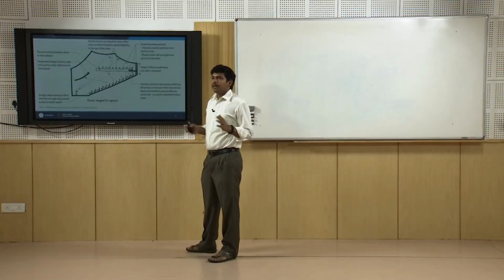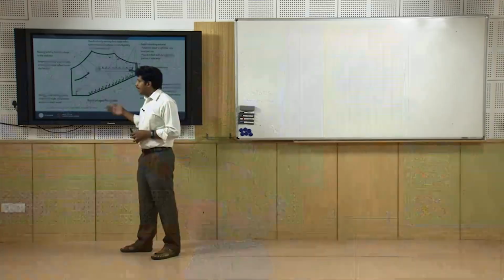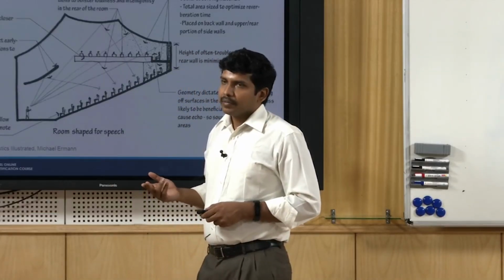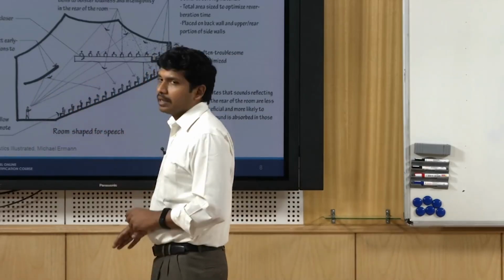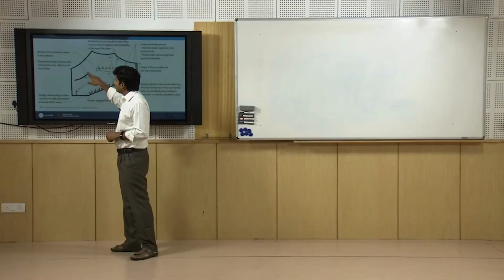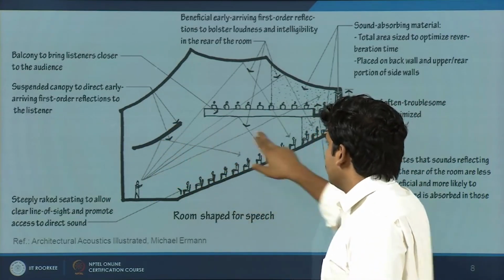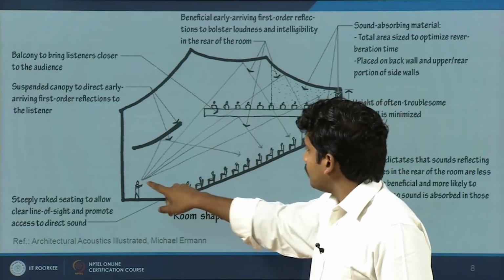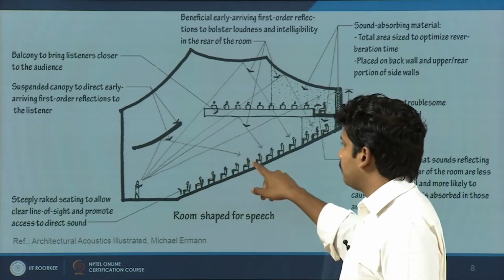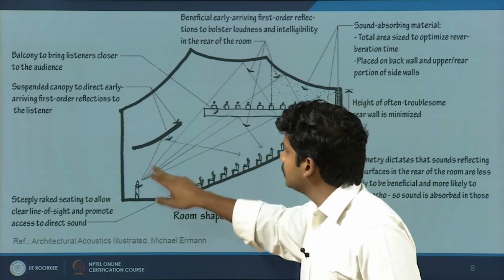For a simple flat plate kind of reflector it is okay, but when it comes to curved reflectors it becomes more complicated. This is called ray tracing, where each and every sound ray is traced. For example, if you were to design an auditorium like this, we would first have to define what the reflections are. If you divide it into segments, each segment would reflect at a certain angle. So if you are interested in a person sitting here, you have to calculate the direct path versus the reflected path. Then take another set, say another 5 rows back, direct path versus the reflected path.